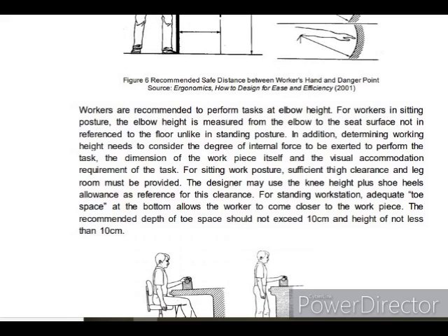Workers are recommended to perform tasks at elbow height. For workers in a sitting posture, the elbow height is measured from the elbow to the seat surface, not in reference to the floor, unlike in standing posture, because in standing posture it is as in the picture.